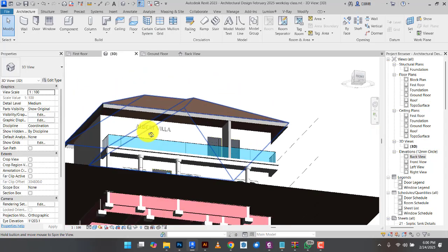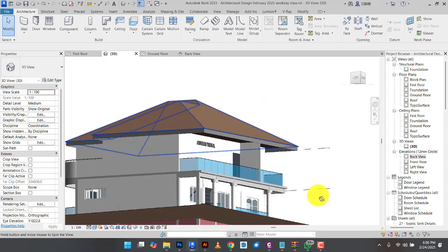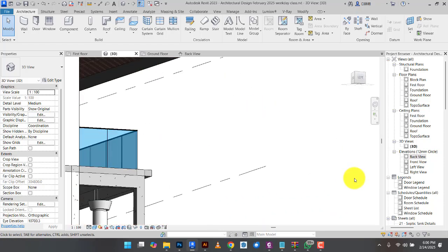The outside ceiling, that's the main work. What you may want to do is to select the normal ceiling and draw it around it to cover everything. And that will make our life simple. I've not done it that way before. Usually you do the normal ceiling and then draw the soffit differently outside. This will make our life very simple.